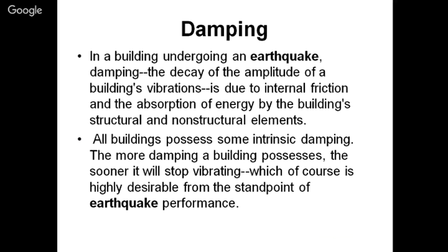Steel has different damping, masonry has different damping, and RCC has different damping. The decay of amplitude of a building's vibration is due to internal friction and the absorption of energy by the building structure and non-structural elements. All buildings possess some inherent damping. The more damping a building possesses, the sooner it will stop vibrating, which of course is highly desirable from the standpoint of earthquake performance.